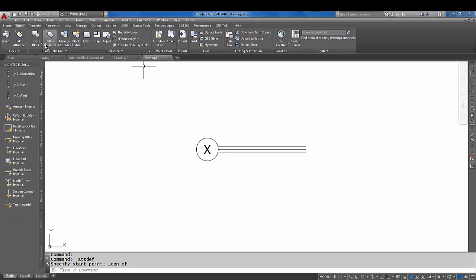And I'm going to use my center O-snap and make sure that that snaps right into the center of the object there. Okay, so now let's make another one.